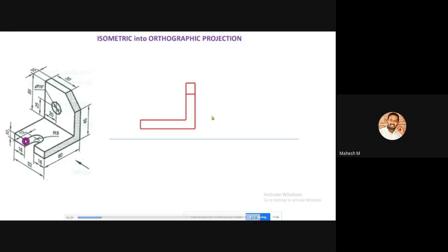Okay, the total entire length of this slot is 20 mm. So please look at the dimension. From the left edge to the center point, it is 12, and the center point towards the right extreme end, it is radius 8. So please add 12 with 8, so that is 20. So you can create a dotted line with a distance of 20 mm from the left edge.